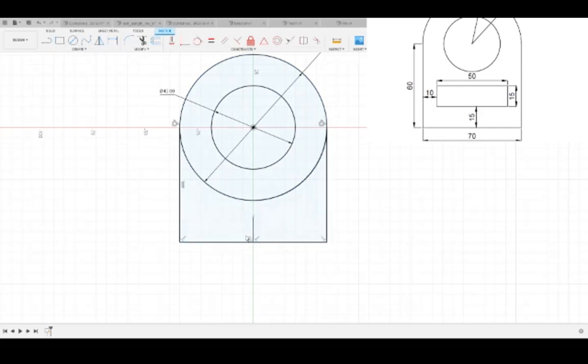This represents that this sketch endpoint is now constrained to the midpoint of this singular line. Instead, we want to define the center line, since, as I mentioned, the center line here is more so implied. That is because if we set this to construction on our sketch palette on the right, this is now a construction line, which is not actually contributing to the model's geometry, but rather acts as a reference for you to put other things on there.